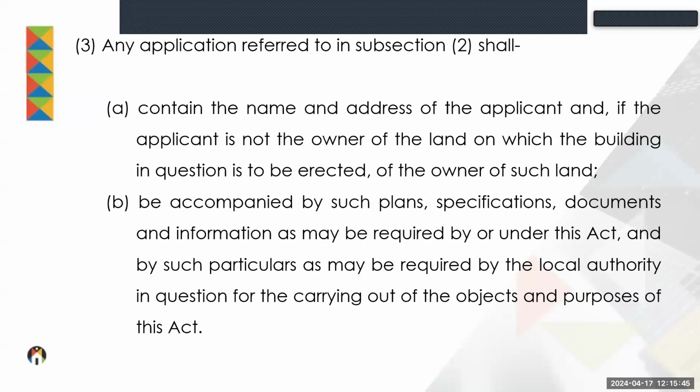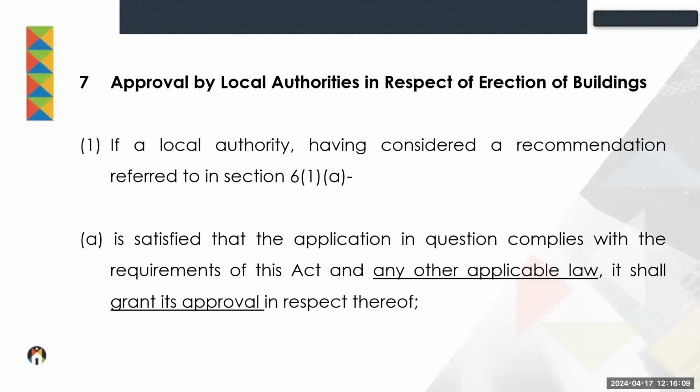In other words, go back to what I've said earlier. What is a building plan? Why do we submit a building plan to a local authority? Because you want to communicate through your drawing to the local authority how you have complied with the building regulations. In other words, you must show through specification of material used, details provided, etc., how you have satisfied the different aspects of the building regulations.